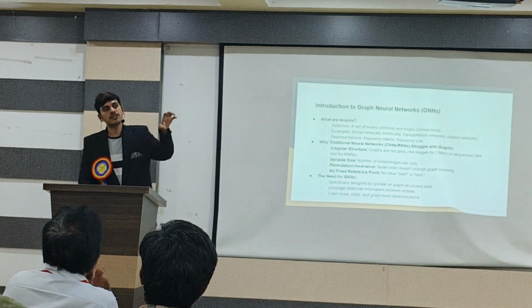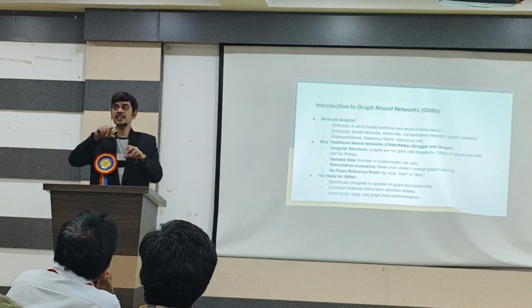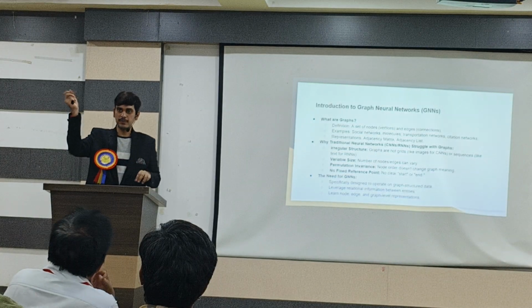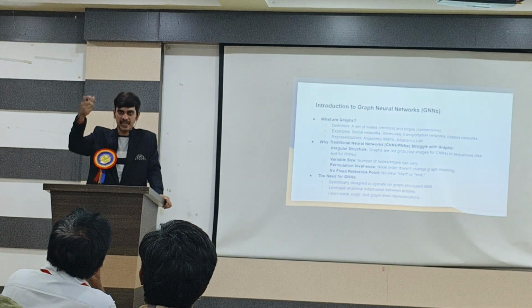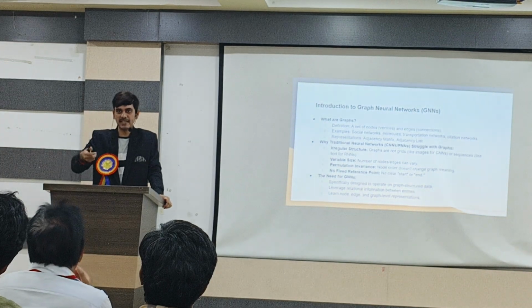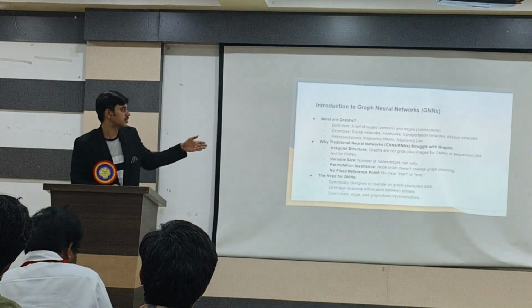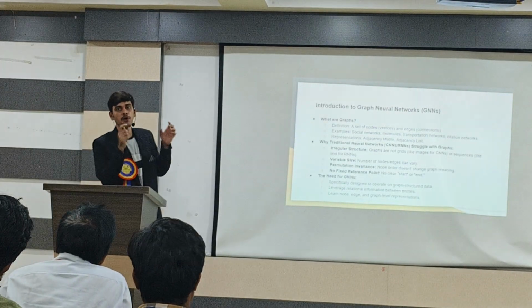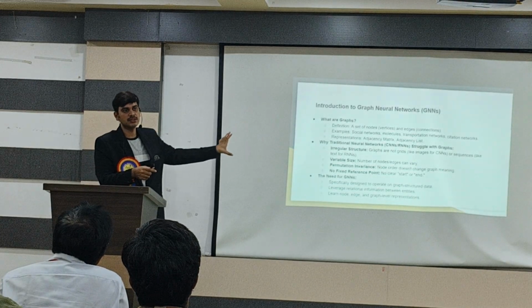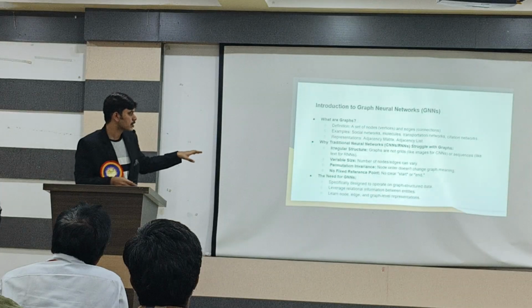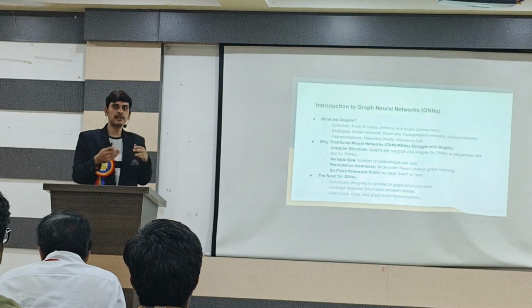If you want to introduce some connection in the VLSI, we can easily introduce one node and analyze data from these interconnection relationships, so that we can predict the timing, the wire length, and the capacitance. All these things we can analyze based on the graph neural network. I told you, if you want to add new cells or a new macro, you can just add it to the graph system so that we can analyze further. There are no fixed reference or starting points; it is variable, not fixed.